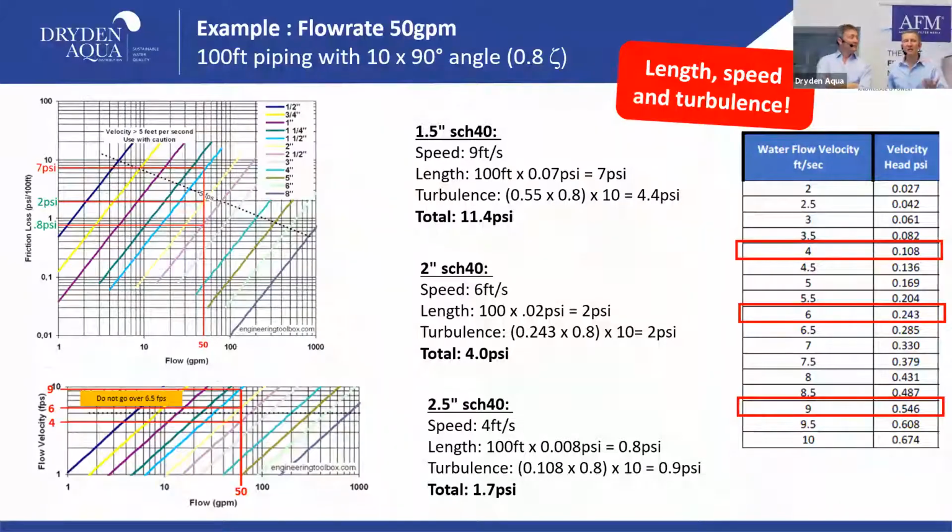Now you can do the same calculation, of course, with 2.5 inches. We're not doing this, this we leave to you. But what can you see from it? What's the key takeaway from this? If you go from 1.5 inches to a 2-inch pipe, you're reducing your friction loss by more than 50%, almost a factor 3 again here. Significant, and this for very little money.